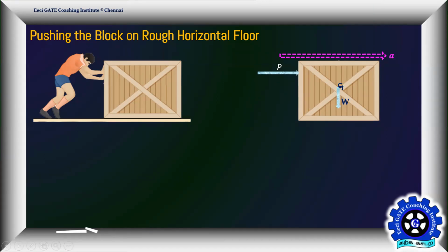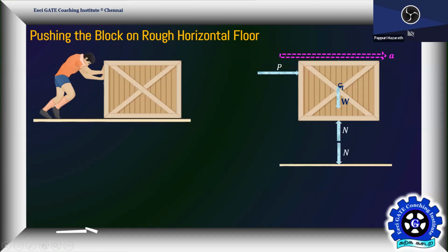At the contact surface, normal reaction will come. Normal reaction always acts perpendicular to the surface. What is the last point? At every contact surface, two normal reactions will come. Both are equal in magnitude, unlike in nature. Unlike in nature means opposite.